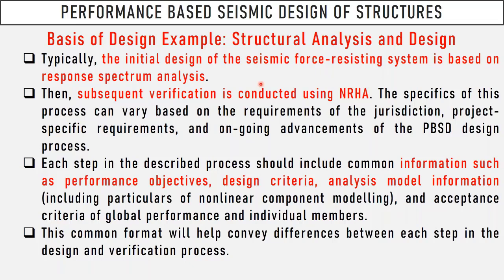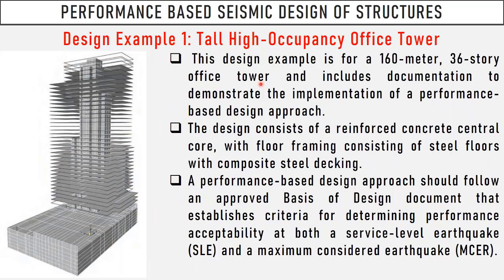But nevertheless, the design has basically two components: preliminary design based on linear analysis, and verification design based on nonlinear response history analysis. And since seismic design is an iterative process, you go from one to another, and at the end, you satisfy all the acceptance criteria in terms of quantitative, not qualitative, parameters.